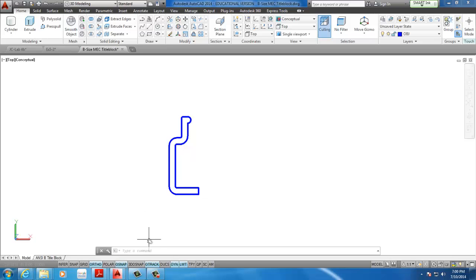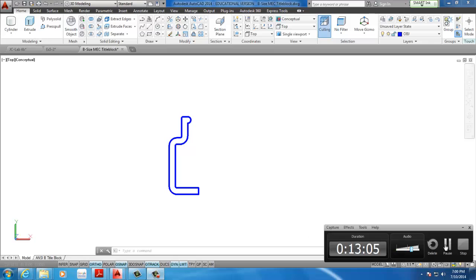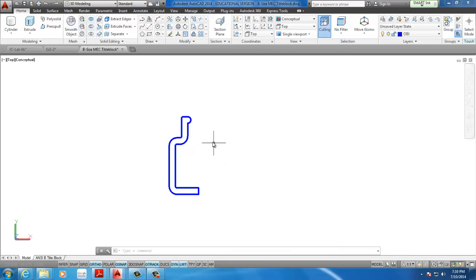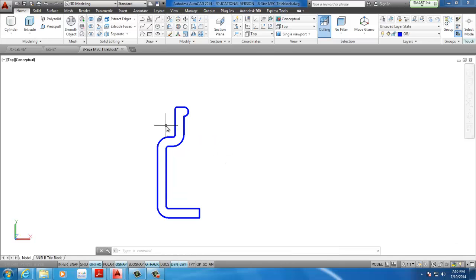Once you have that, we're going to do some other steps to create a 3D object. So hopefully you have this set up already, and there's going to be 3 ways of doing this. I'll start with the easiest way, which is create this into a region and then revolve it. The other option is to use p-edit and revolve it. Actually, there's 2 options. We're not going to use the press tool, because it wouldn't work here.